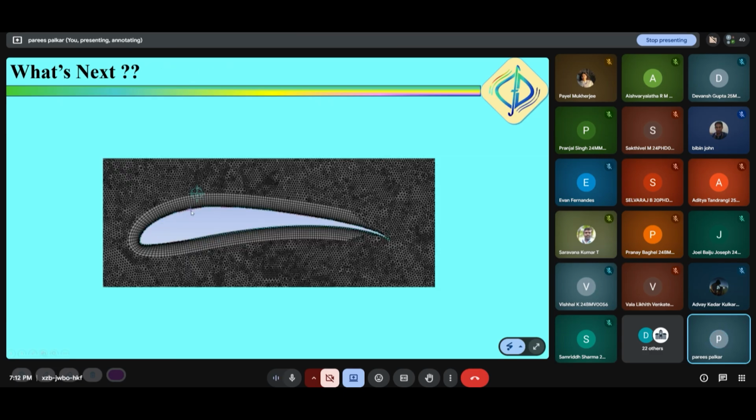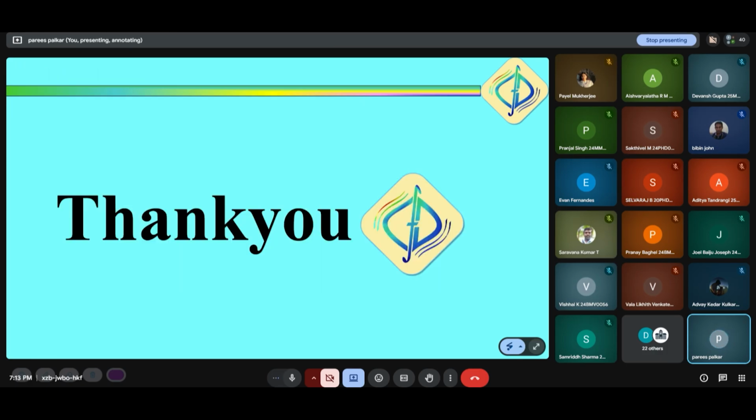I also have an airfoil geometry with me that has been run on OpenFOAM 9. This is an S1223 airfoil, and I got some triangulation errors while importing to OpenFOAM, but I resolved them using OpenFOAM, though Fluent Meshing was not able to. I'll be sharing that file as well. If you are interested in meshing the airfoil, you can take this up as an assignment.